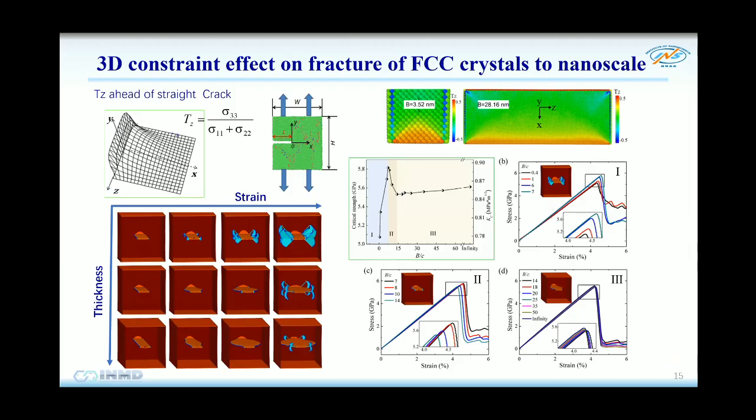And this is about tens of nanometer thin plate with a crack there. And when we load this, the microplasticity occurs, and they load like this way. And this is thickness, and this is the toughness. You see the toughness depends on the thickness even below 10 nanometers in thickness.